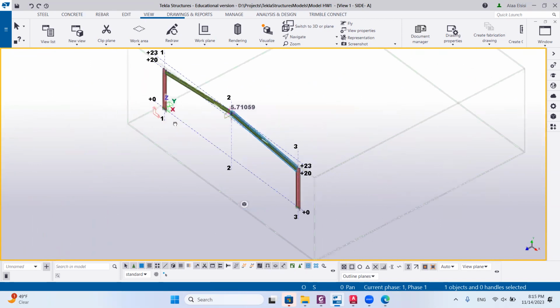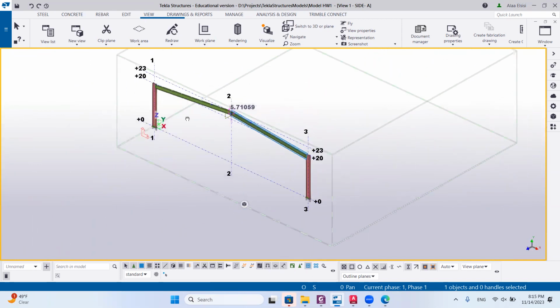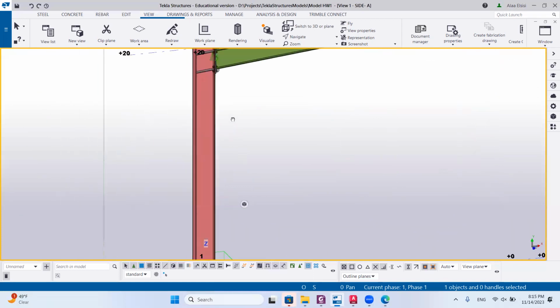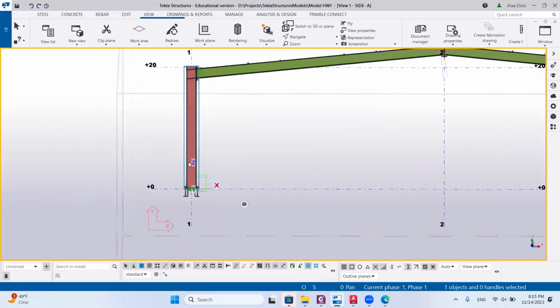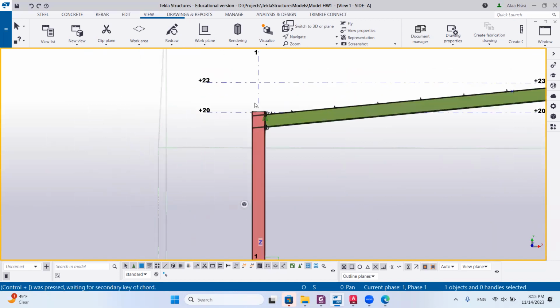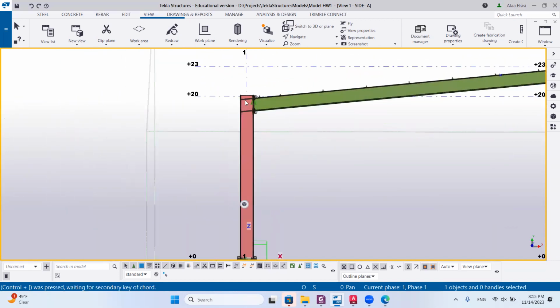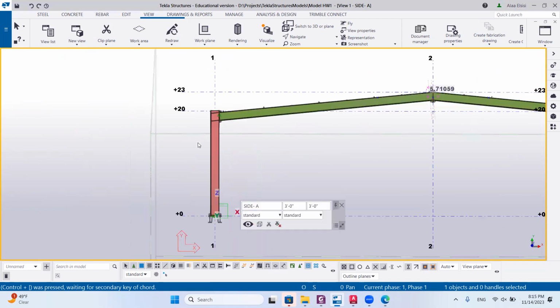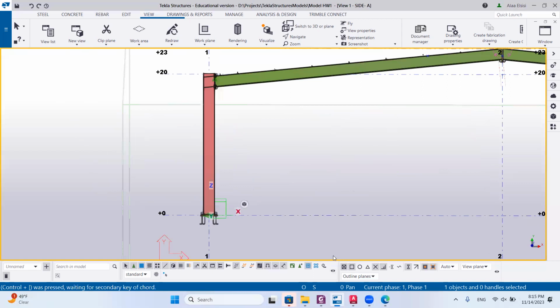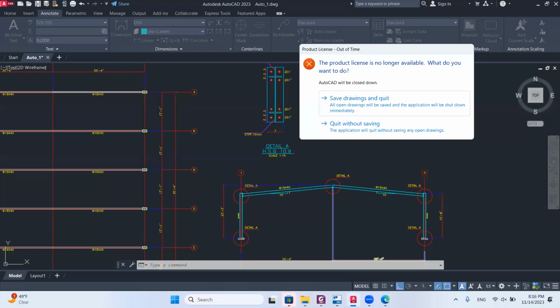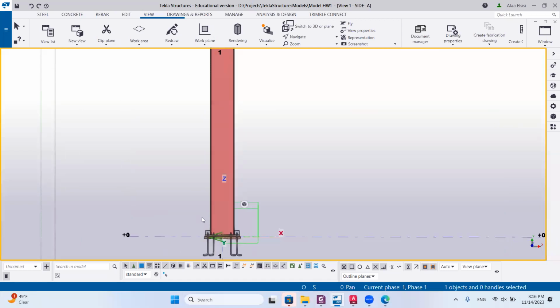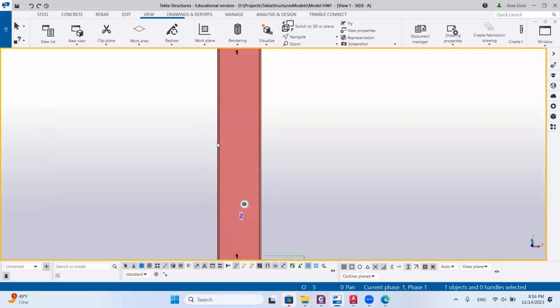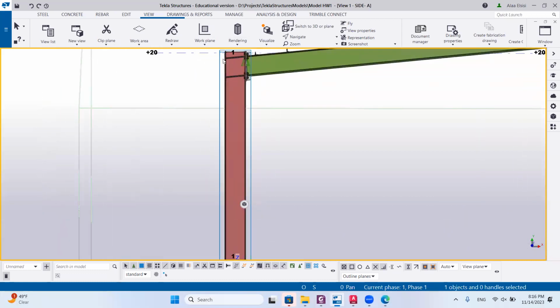So now we are ready to replicate our frame. We have everything we needed. No, we still need to add seat angle for the side girts. So let me look at this in the drawing. We don't have any details on the drawing, but we usually build something around 15 foot of masonry, and after that we start to put the steel wall.